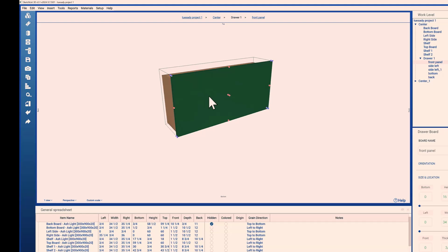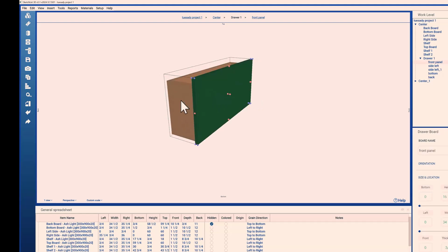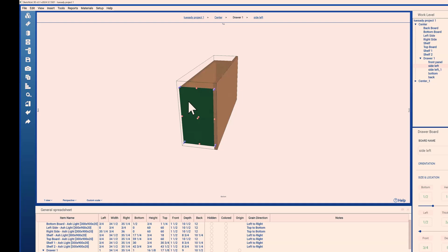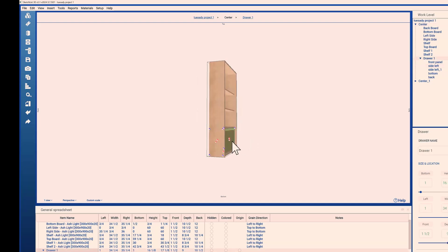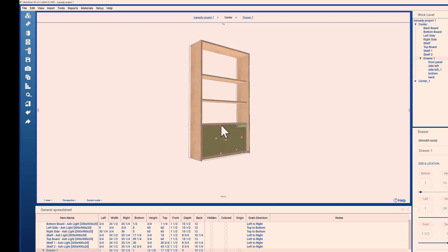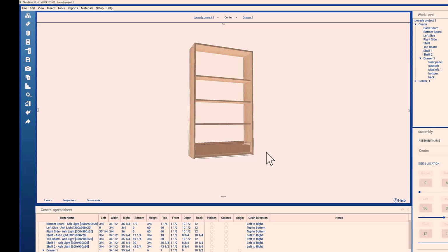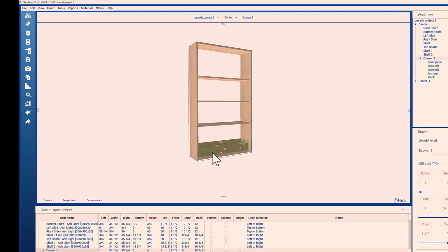Then when I pull it out for my next project, assuming you more or less make things the same way all the time, you could pull it in and say, now I need it here, it's going to be a 6-inch drawer. You don't have to remake it. You just take what you have in your library and modify it. That's one of the big time savers.